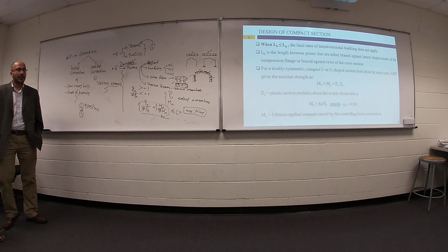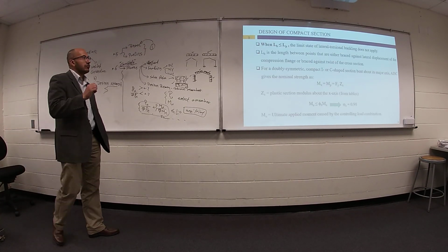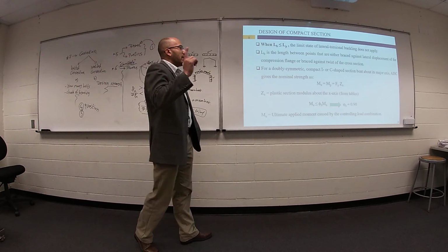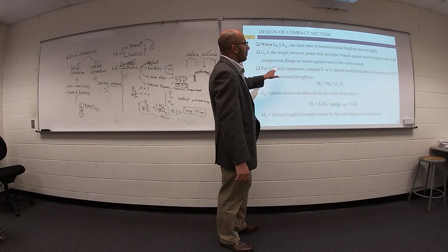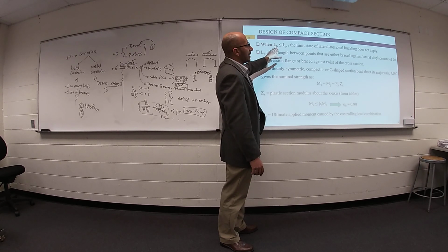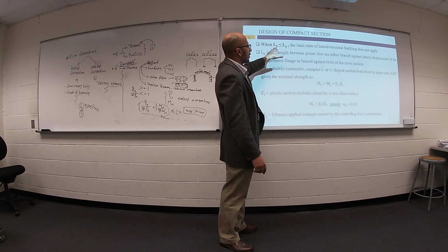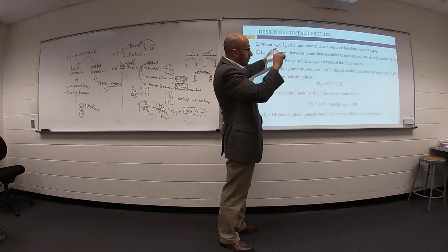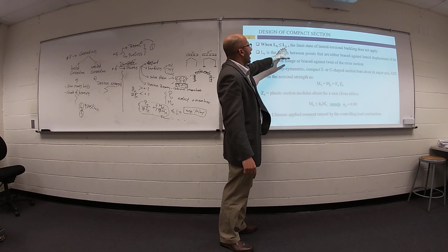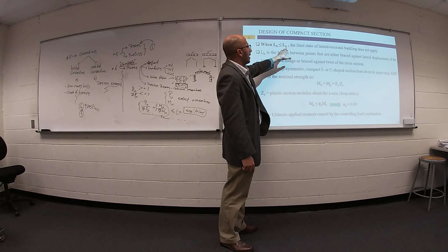For design of a beam, you first need to think about the relationship between the unsupported length and LP, to avoid lateral torsional buckling. What is the relation between these lengths? You need to read your problem carefully, and find the value of LP.